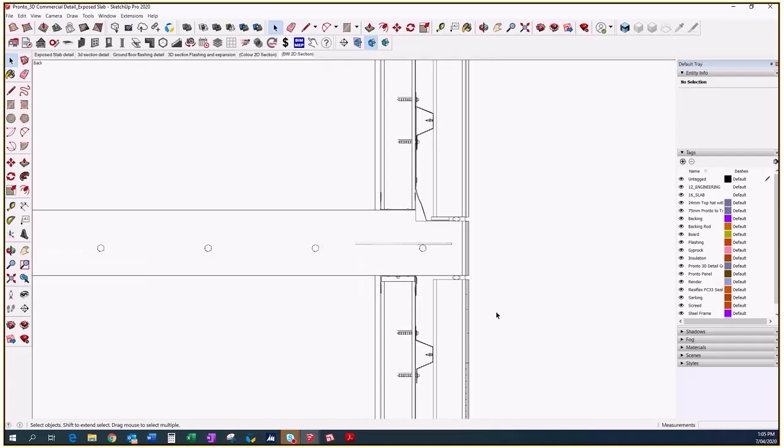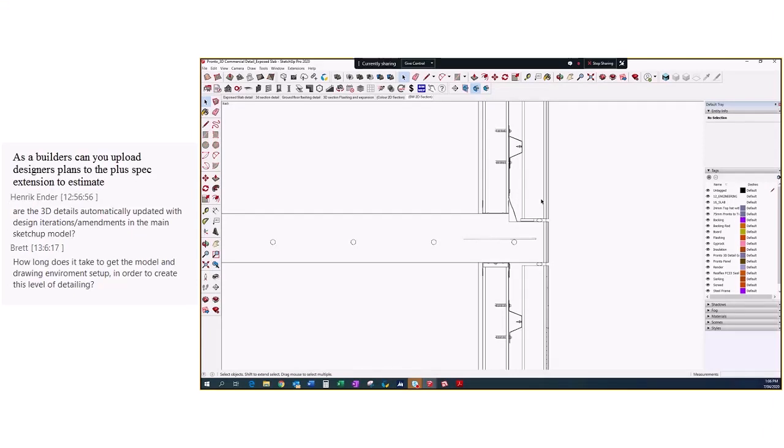However, again, with a simple change, all you're doing is turning off color and texture. And when you would go in and turn that into your 2D detail, you could either reproduce it from scratch in Layout, like the traditional AutoCAD way where you're drawing each line from scratch, or you're just using the 3D detail and choosing what lines are at what weight, drawing over and masking elements that you don't need.